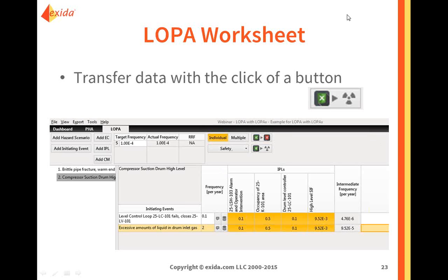The example was this: I have one measurement. That one measurement goes into the control function, or the control system, I should say. Based on that one measurement, I'm either operating a valve, and at the same time, I'm sending an alarm for an operator to do something. The operator action is based on the same process value measurement as the control function action. Therefore, they are not two independent layers of protection.